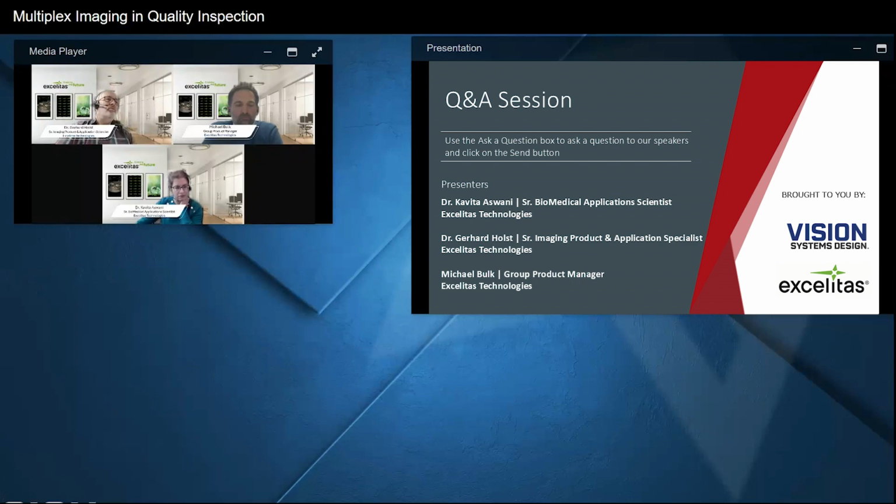Therefore, the real resolution is a third of what the number of pixels is. If you switch to changing the illumination, then you can use the full resolution. Therefore, if you use a switching illumination and a monochrome sensor, then you get a higher resolution for your color images.